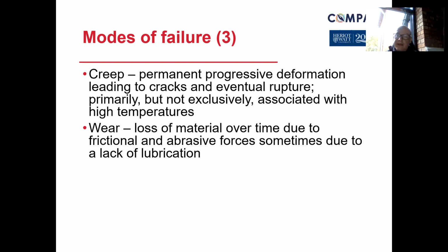Now, it could be as a result of damp. It could be as a result of water and weathering coming up against that brick wall. And as a result of those abrasive forces, it can change the mortar mixing and cuts into it and bits fall out. If you think about it, sand and cement is in there.